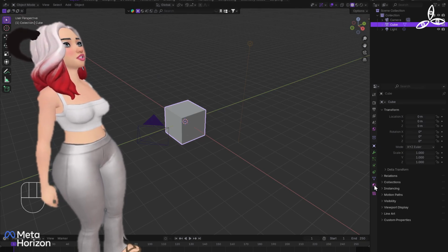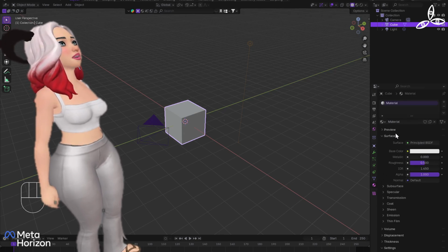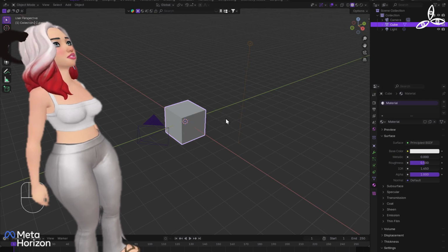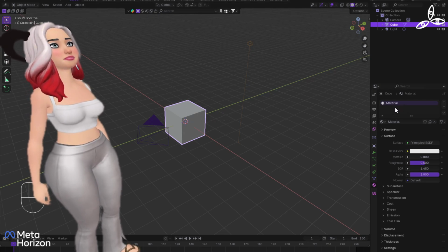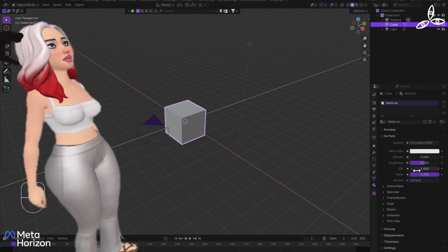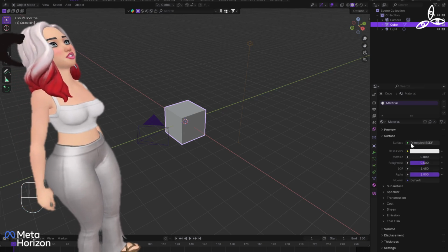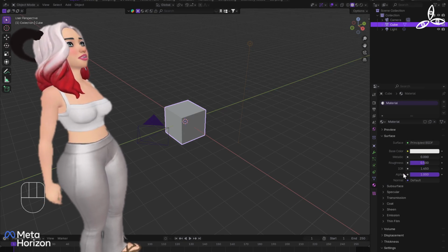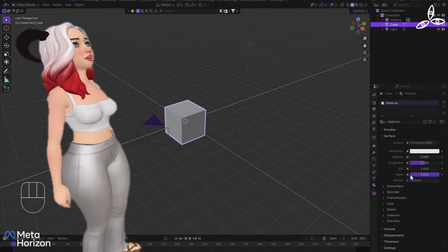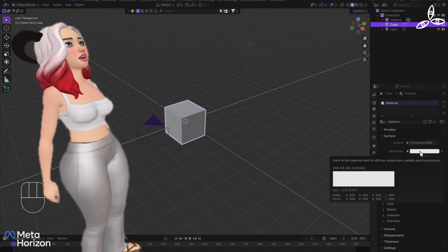And then if I go down to this little button just down here, this little pink sort of orb almost, if I click on that, that is actually the material properties section. If I go in here, you can see that the box has a default material already, and it's called material. With that material assigned, I've got a whole load of things in here. The default at the moment, this is Blender 4.2, uses a principled BSDF surface, which provides you with a whole lot of options. But really, we're not going to worry about that.